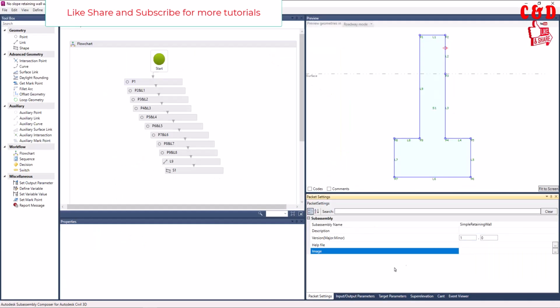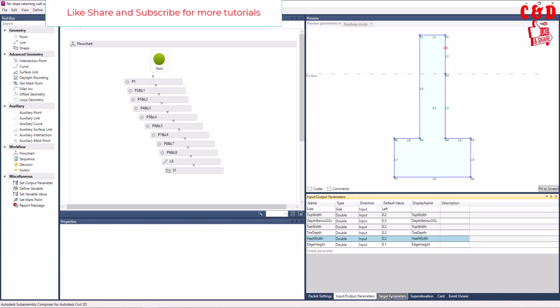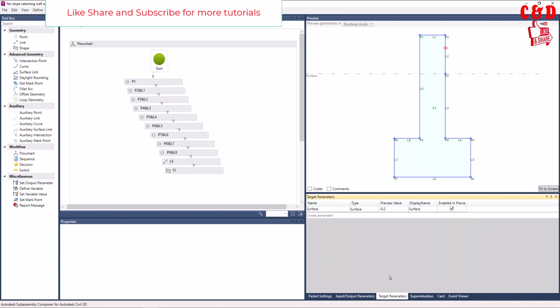Let's go to another tab, target parameters. For this case we have only one target parameter and that is sufficient: the surface, the original ground level. This target parameter can be of three types. It can either be surface, offset, or an elevation. For this particular case we are only targeting the surface.